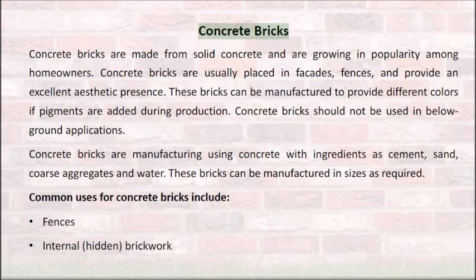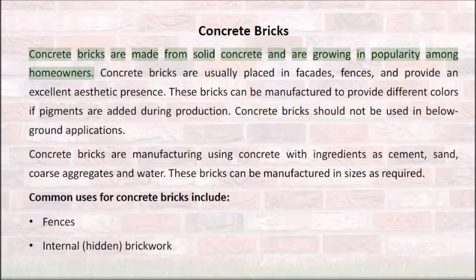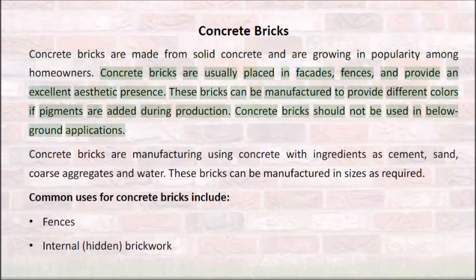Concrete bricks. Concrete bricks are made from solid concrete and are growing in popularity among homeowners. Concrete bricks are usually placed in facades, fences, and provide an excellent aesthetic presence. These bricks can be manufactured to provide different colors if pigments are added during production. Concrete bricks should not be used in below-ground applications.